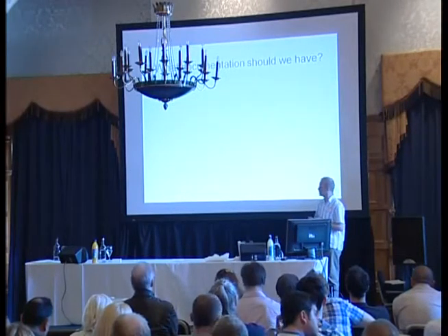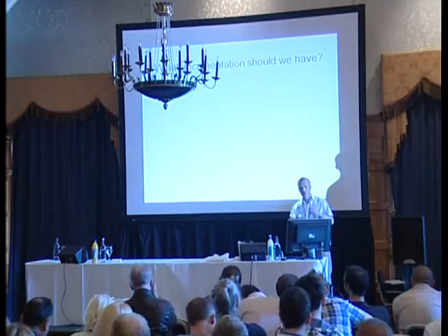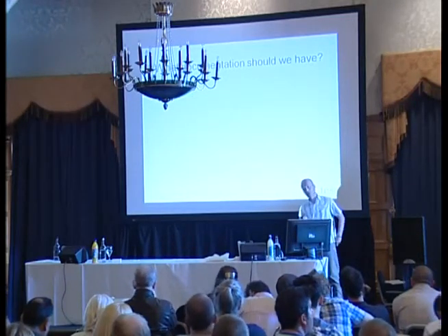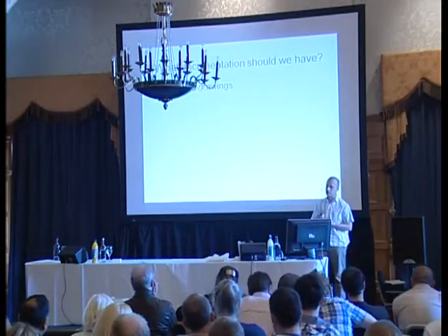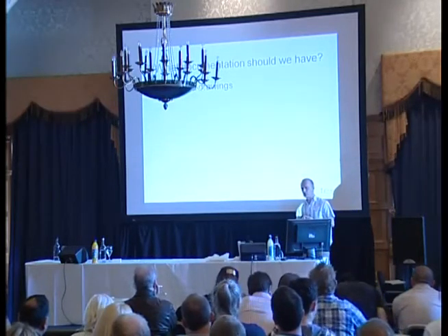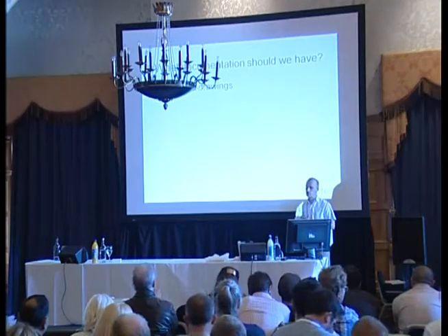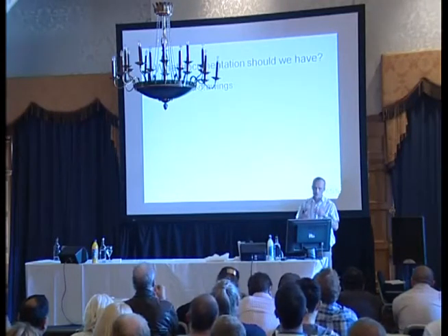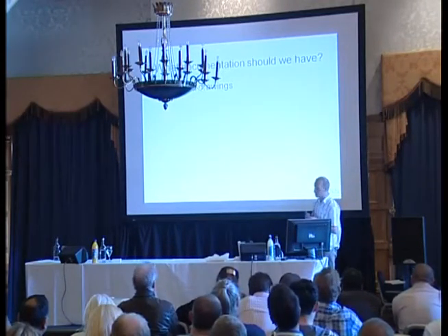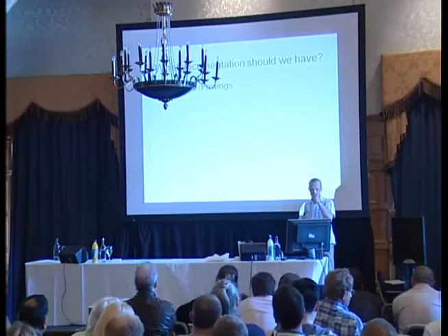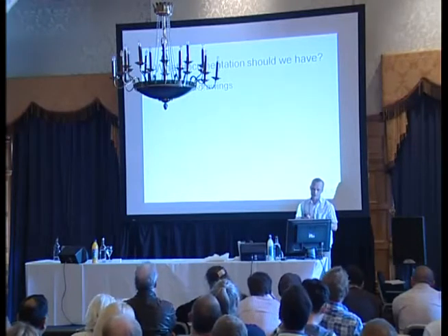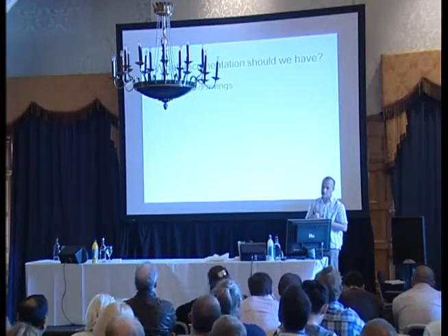So what documentation should we be looking for? Well, obviously that's a lot of what we've been talking about this morning. And I would say the first thing that I'm looking for, if I'm the safety officer on a site, is structural drawings. Obviously now, maybe what we should be asking for is full 3D rendering and lots of pretty load case dynamics to show us where things are and what things are doing.